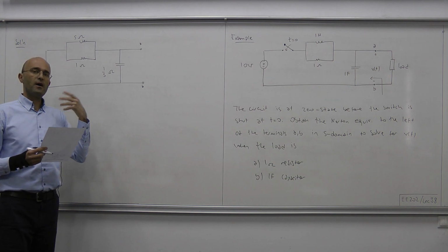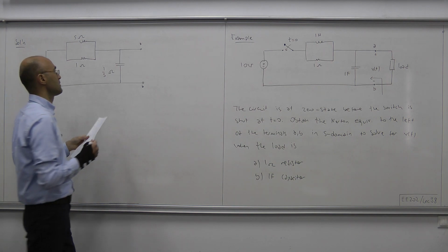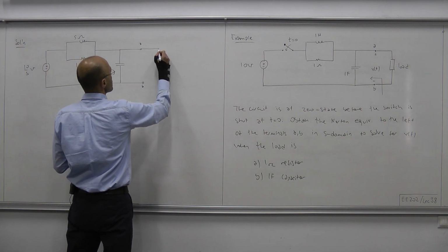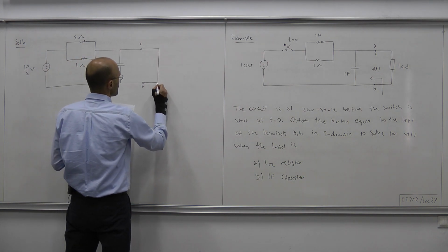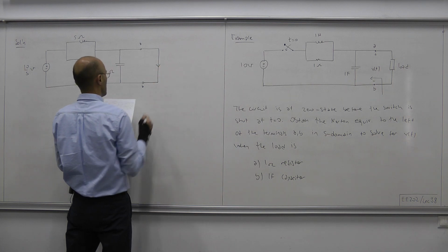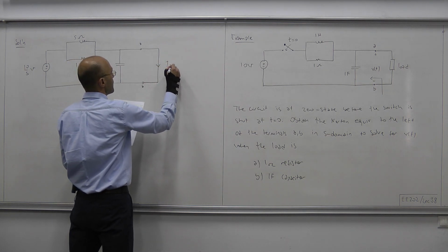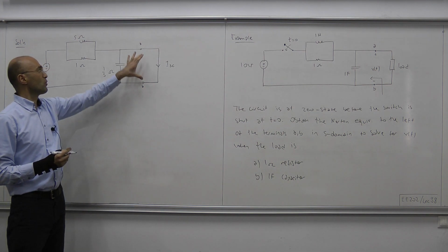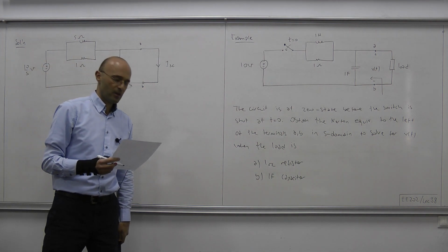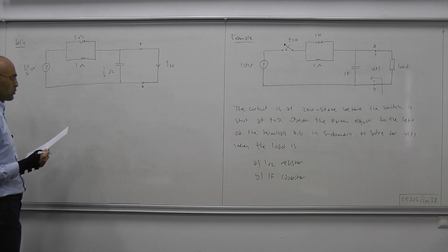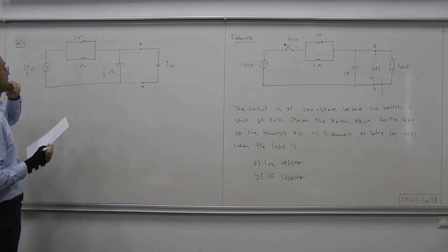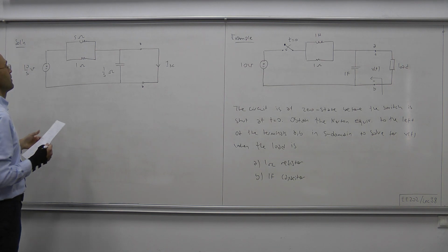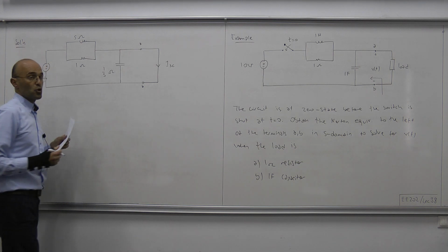Okay. Now, for this circuit, we're going to compute the Norton equivalent. So that means we have to figure out the short circuit current, which will be our Norton current. Okay. And we have to figure out the Thevenin impedance seen from the pair of terminals A, B. So let's begin with computing the short circuit current. This is the circuit in S domain with the terminals shorted.